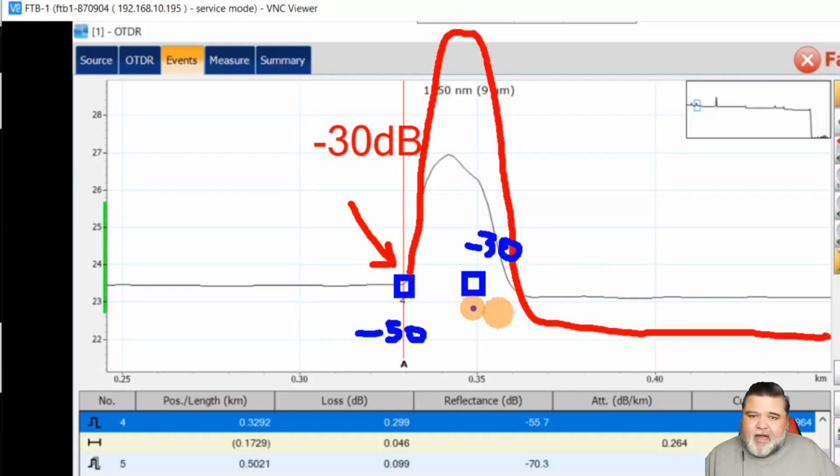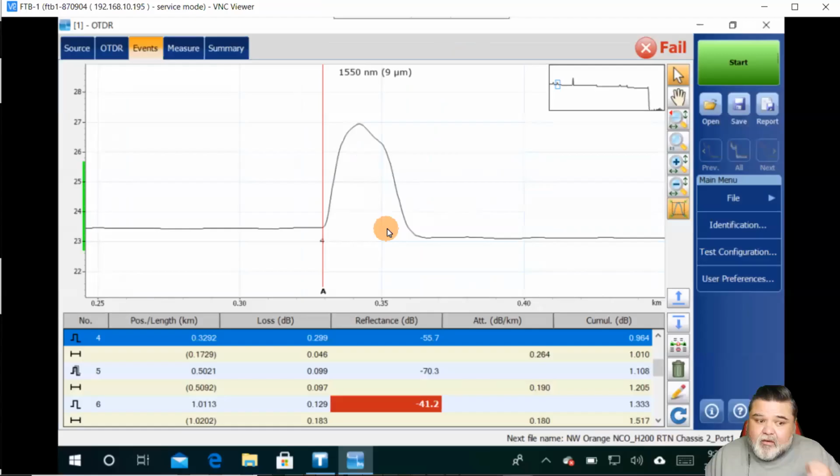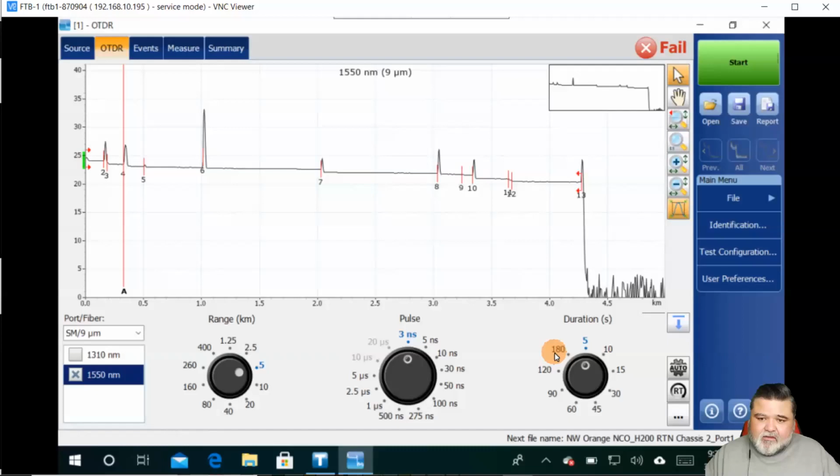And to pull in duration here, if I were to set this trace at 3 nanoseconds for 5 seconds, a very short pulse width, I can see events over time. Our OTDR has a 4 hertz analyzer, meaning 4 times a second. At 3 nanoseconds it looks like this all the time, and it's just noise. The software 4 times a second looks for movement, looks for noise, and flattens it out every time it sees something moving.